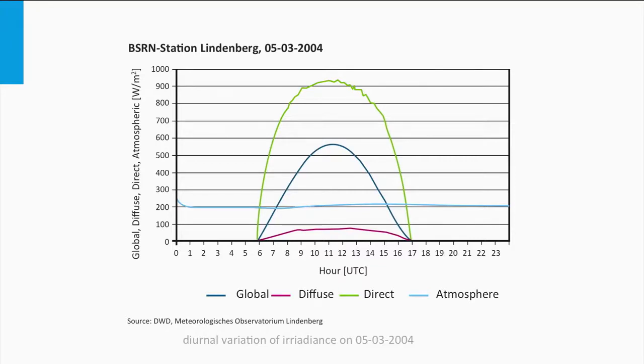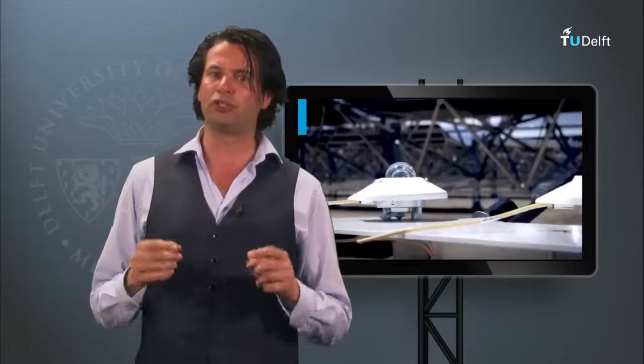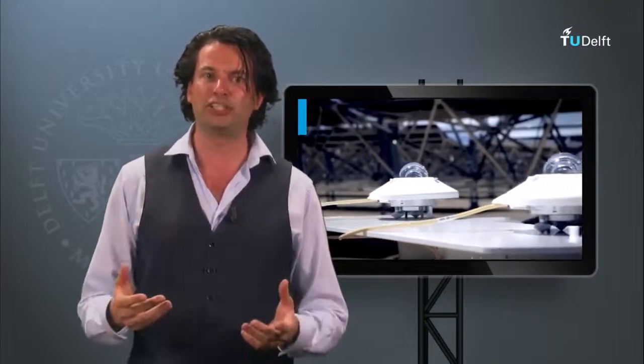It consists of direct normal radiation from the sun, indicated in green, and the diffuse radiation from the sky, indicated in red. In weeks 7 and 8, we will talk about PV systems. You have to realize that the response of a PV system differs between diffuse light and direct light. This week, I would like to show you how we can measure the irradiance of direct light and diffuse light. For that, we use a pyranometer, and you often see these tools installed next to a PV system. These are instruments used to measure the heating power of radiation.